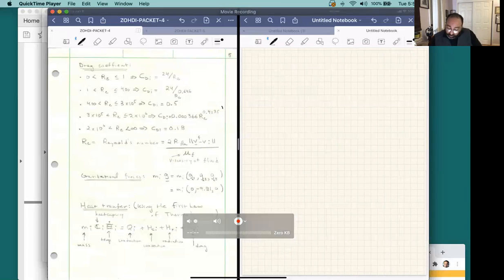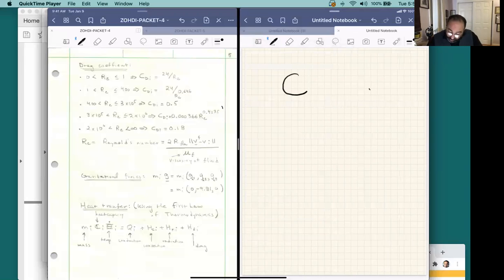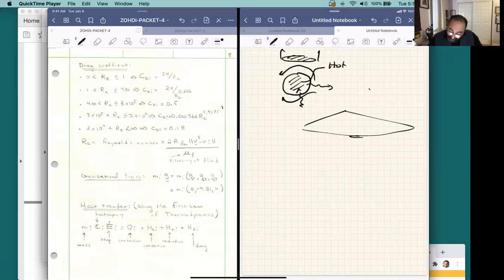So in the wonderful world of heat transfer, we basically have the following situation. We have an object, and that object is going to exchange heat with its surroundings. So the heat might go in and out. It also may have heat due to the drag forces. It may also have heat because initially when it gets pushed out of the extruder, it's already hot. So our problem is, how hot is this thing going to be when it hits the target way down here? So the governing differential equation for this is that we take the mass of that same object.